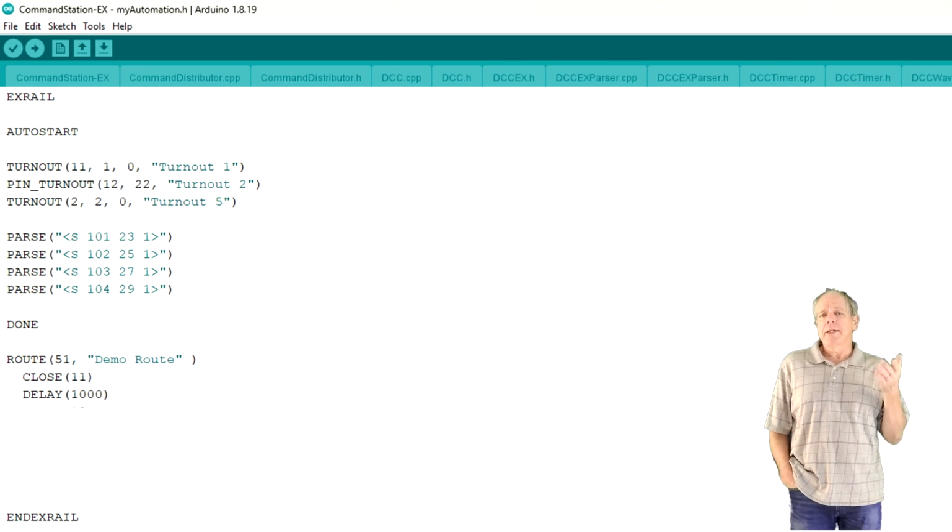It just stops the execution of this particular sequence, but has no impact on all other sequences or the Arduino program itself. I point that out because if you ever took some lessons about programming in Arduino, most likely you were taught that using the delay function is a real bad idea because it stops the execution of the entire sketch. And generally this is the case, but in the XRail script it is safe to use delay.